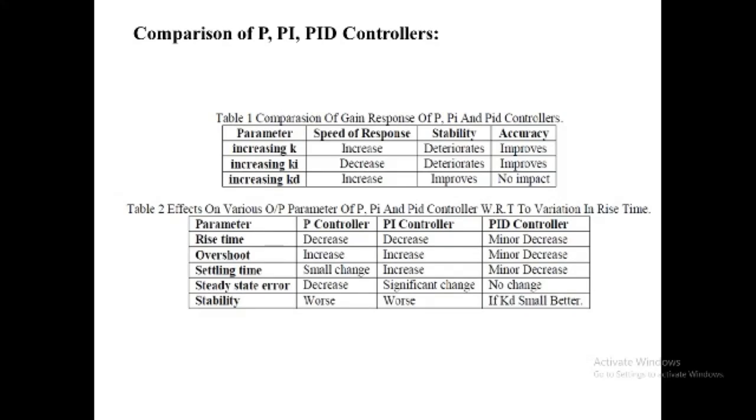Derivative control is used to anticipate the future behavior of the error signal by using corrective actions based on the rate of change in the error signal. The control signal is proportional to the derivative of the error, and Kd is the derivative gain.